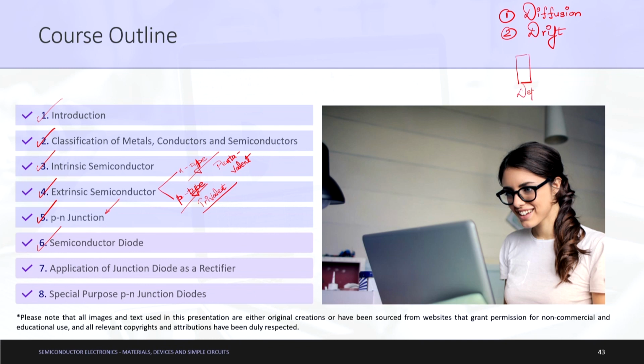So, this was your depletion region. Let us say this is the complete PN junction and this depletion region was created, and in this depletion region an electric field was set up, and inside that a drift current was flowing. Initially the diffusion current is small, and then there is a time when equilibrium is reached, when the diffusion current is equal to the drift current, and then there is no net electric current passing through the circuit.